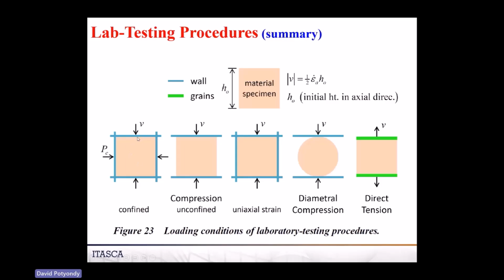Notice that we're moving both the bottom and the top. We're doing this on purpose because that way we can put a measurement circle in the middle, and the middle of the specimen, as we load it, is not going to move. If we just pushed it from the top, the whole system starts to move down. So to keep everything symmetric, we load from above and below.